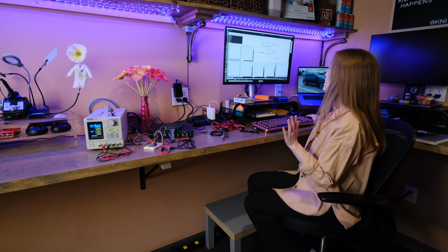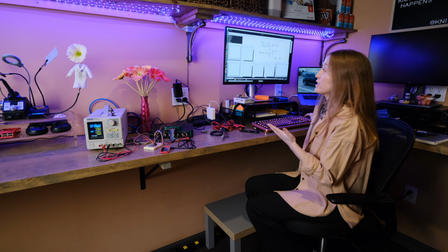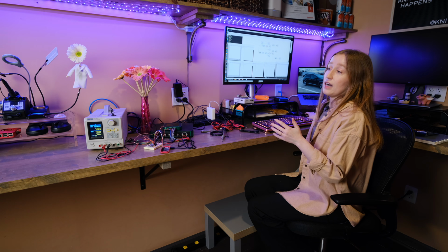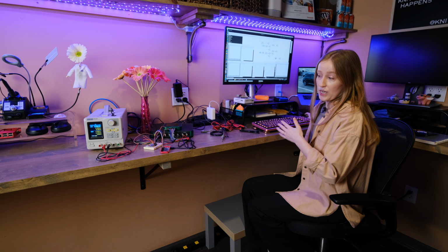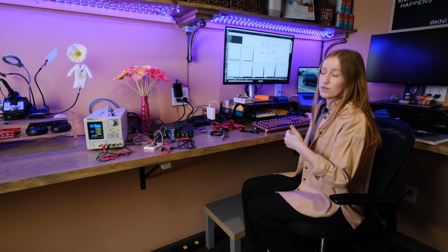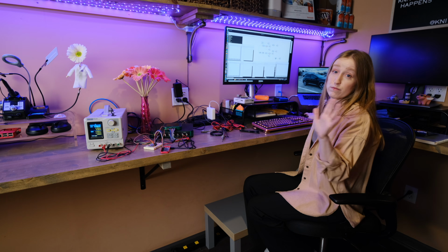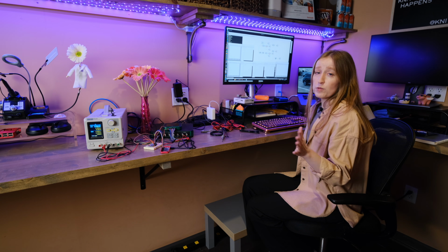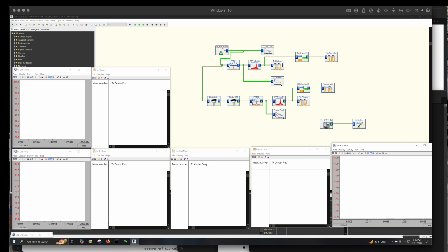That's my first check. I then put it through a Fourier transform so I can view that same raw signal in the frequency domain. That way, when it's unfiltered, I can see everything. Are there any spurs? Are there any harmonics? I'm visually assessing this at this point. Is my center frequency anywhere close? In further processing, I'm also applying the equivalent of a peak hold on an oscilloscope.